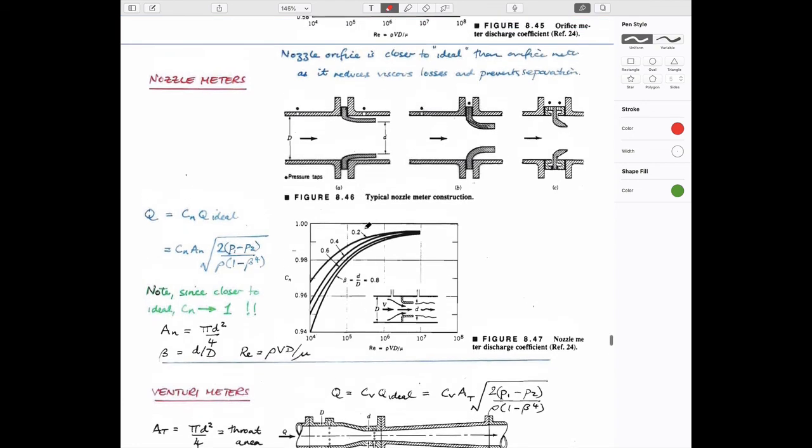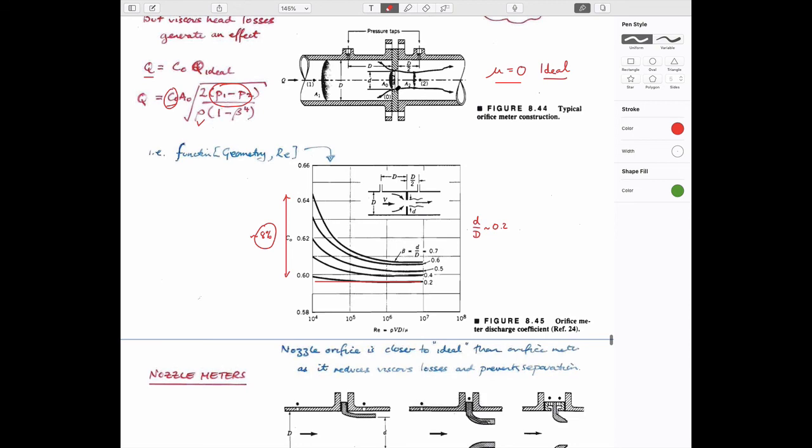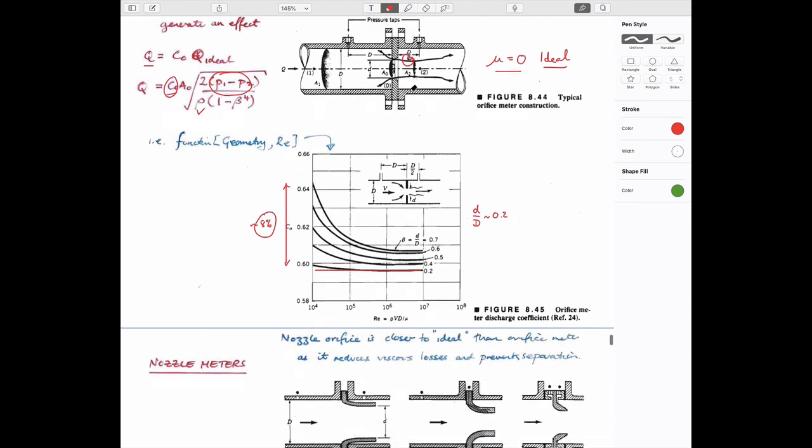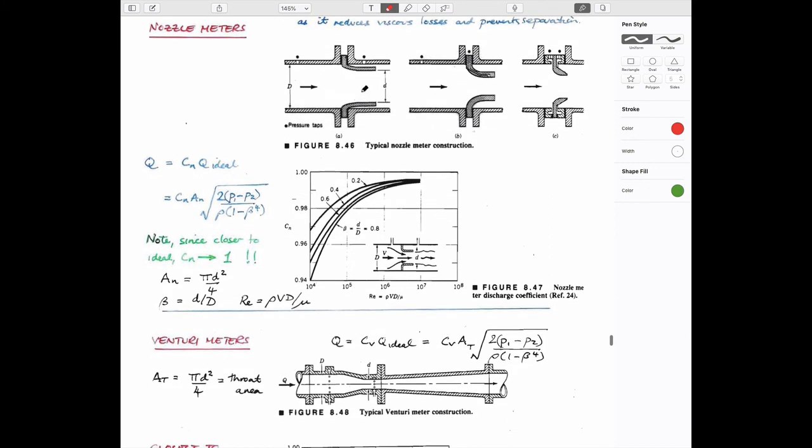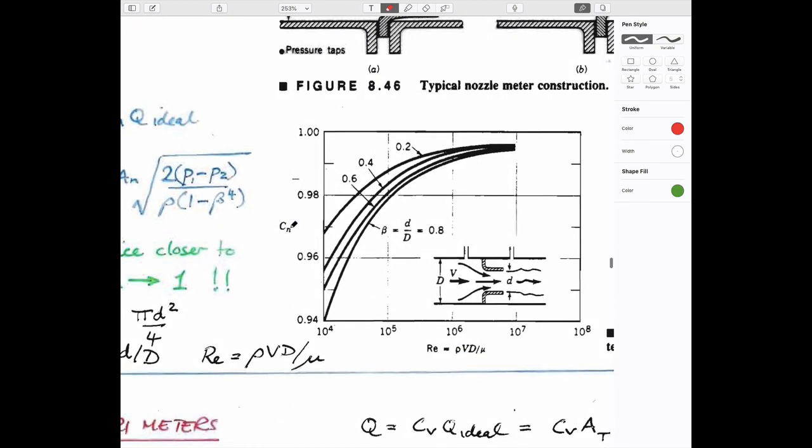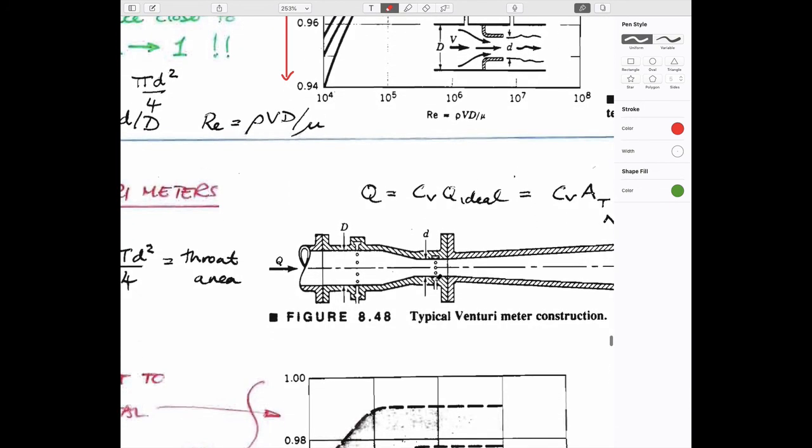If you want to make a less disruptive flow, instead of having a plate in the flow that would have these eddies that exist behind it, you can make a Venturi type meter which has a smooth transition. And you see that if you do that, then this correction factor changes again to range only by something like 6% in this particular case, and again be relatively flat for some portions of Reynolds numbers. By making it smooth, the correction is very close to an ideal fluid, an inviscid fluid. And so you can design your flow meter, if you like, to have as little disruption as possible.